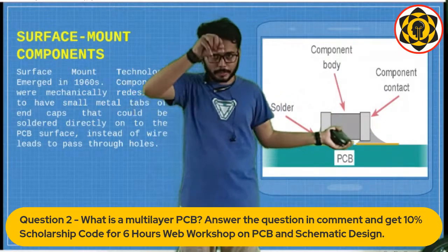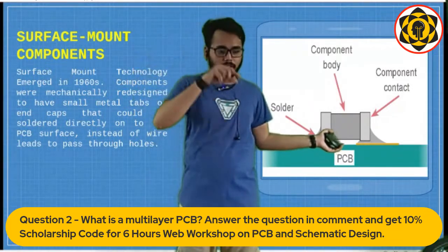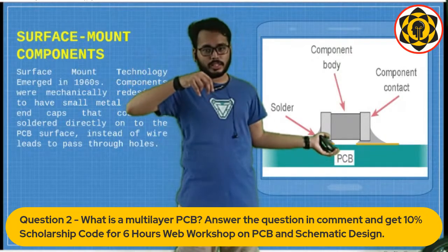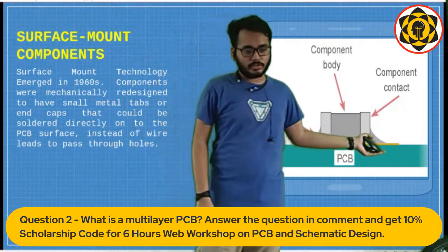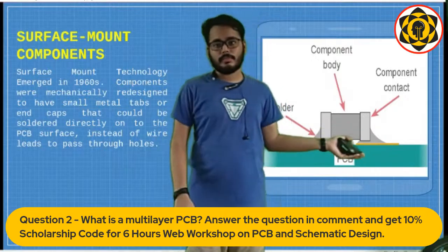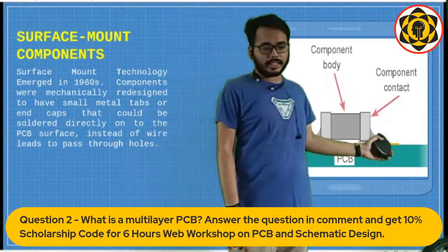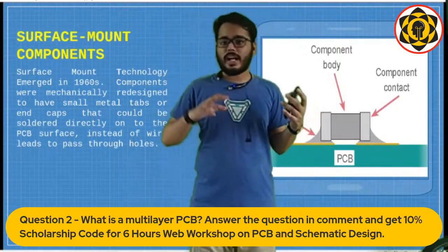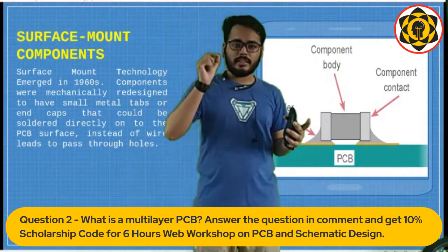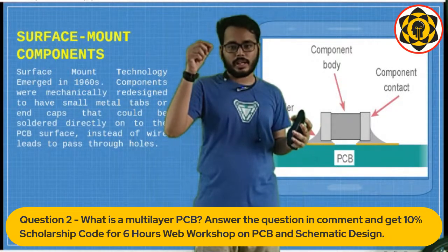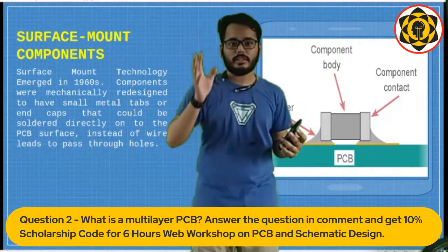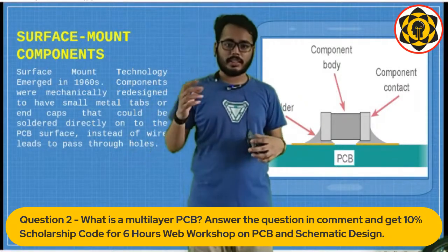So basically, there are small copper pads on the PCB, and you place a component on there, and then you place some liquid solder and heat it to melt it and fix it there permanently. These are the contact points where you place the solder. Since these are such small contact points, a soldering iron usually cannot be used, because the tip of the soldering iron, no matter how thin, would have a little bit of vibration, because our hand has a natural frequency. You cannot keep it absolutely still. It's very hard. So an easier way of doing this is called solder reflow.